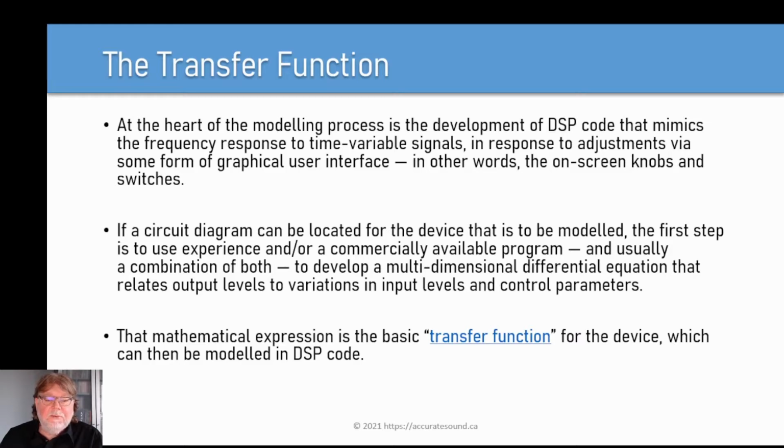Now, if a circuit diagram can be located for the device, then we can actually build the circuit using software simulators, DSP simulators, and it's able to produce a multi-differential equation that relates output level to variations in input levels and control parameters. That mathematical expression is the basic transfer function for the device, which can then be modeled in code. For example, the JUCE C++ audio framework, which is quite mature, has all the classes necessary to develop just about any kind of DSP software one wants.